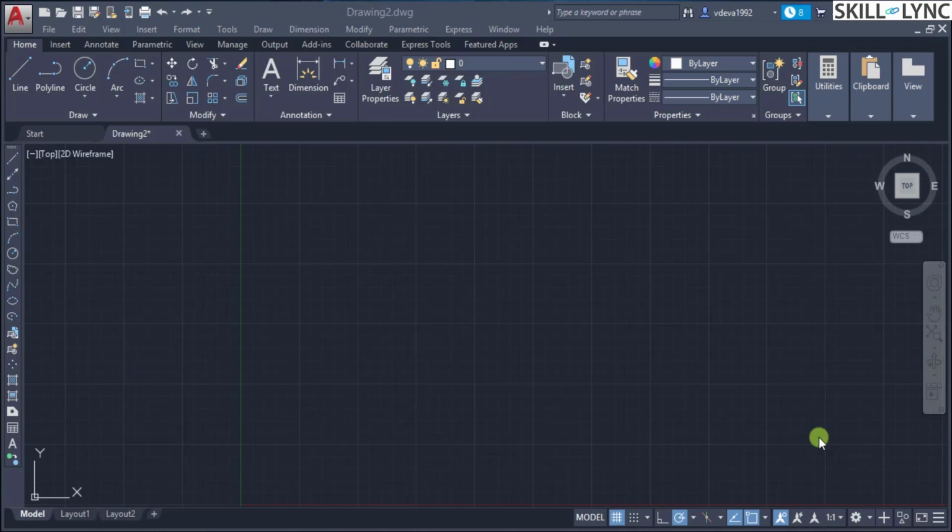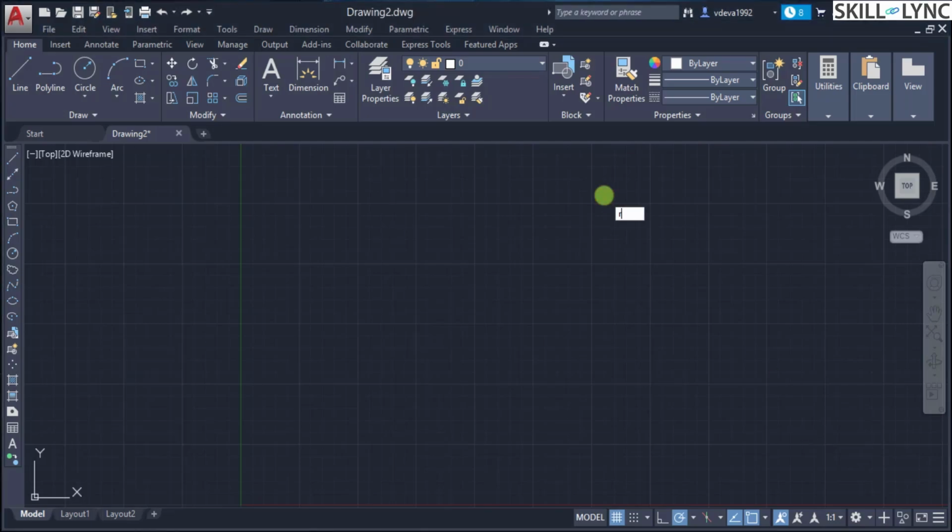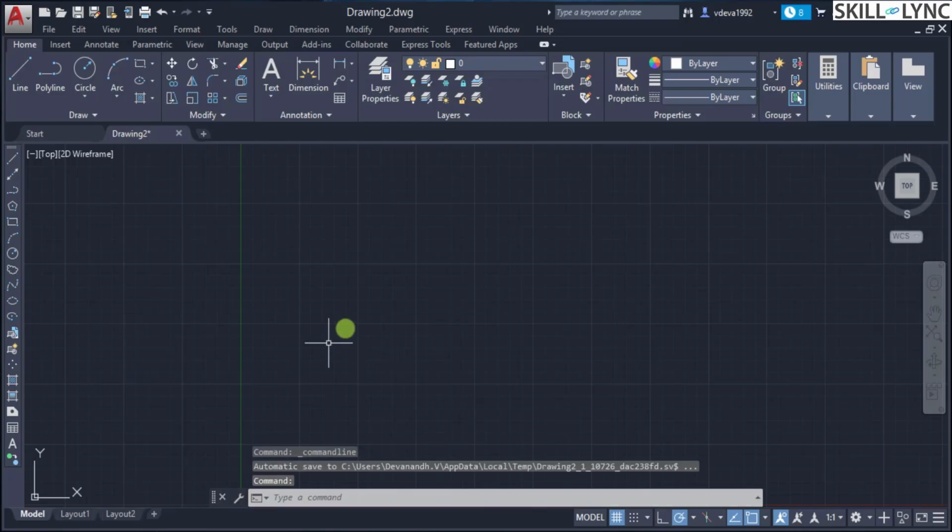Towards that, let us quickly draw a rectangle to drive that point. Let me quickly go through the dimensions initially and then later come back again showing what the individual dimensions are so that you can make a note. First let us draw an A4 size. We'll use the rectangle command to randomly specify a point. As you could see now, I've taken away the command prompt for faster access. You can enable it on or off by using the hotkey Control plus 9, because sometimes it might delay the processing of your graphical cursor movement.